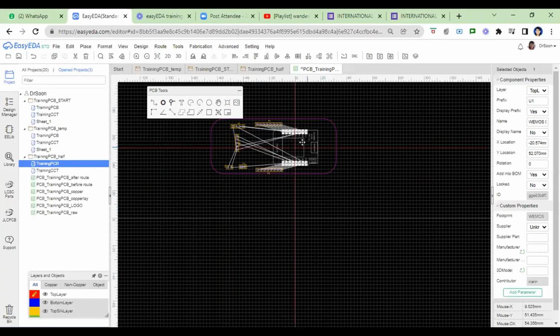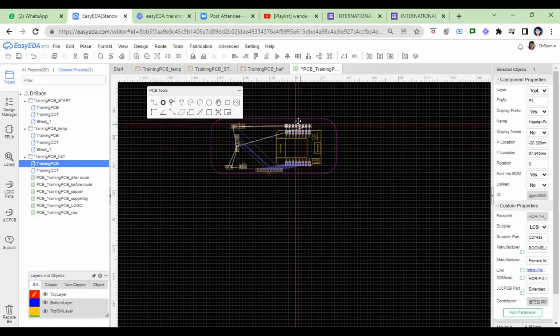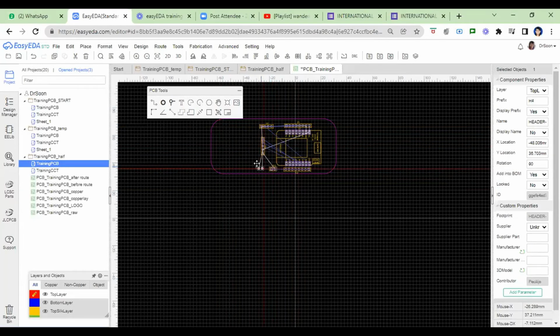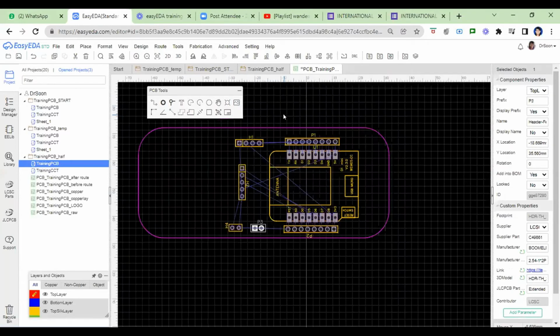All right, so you can move the components around, positioning them to a suitable position for your connection to the peripheral wiring. Maybe you have connectors. You must have a good idea where you want to put the connectors and the components. Probably you want to leave some space for strain relief for your cables here.